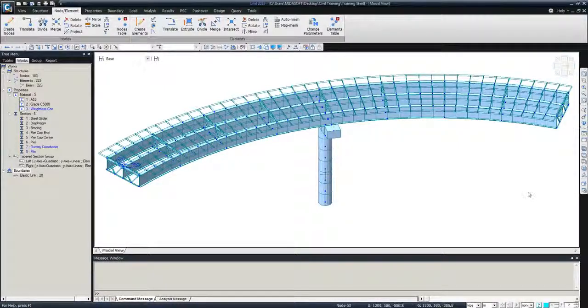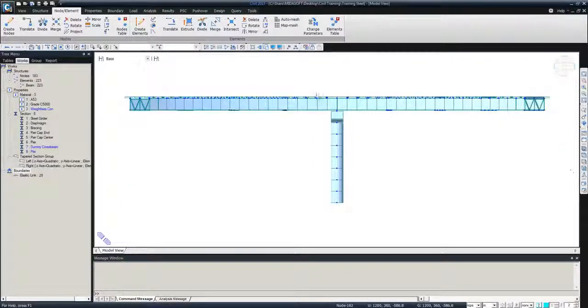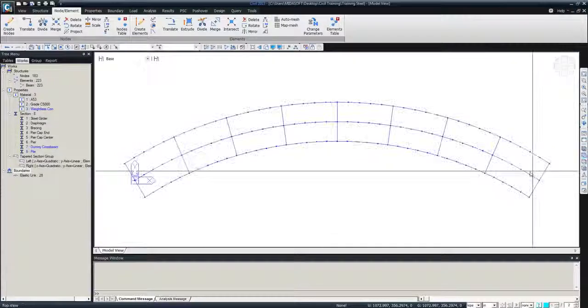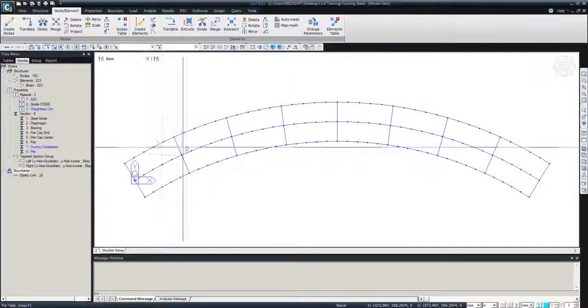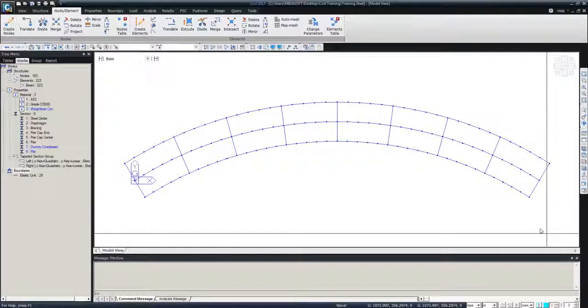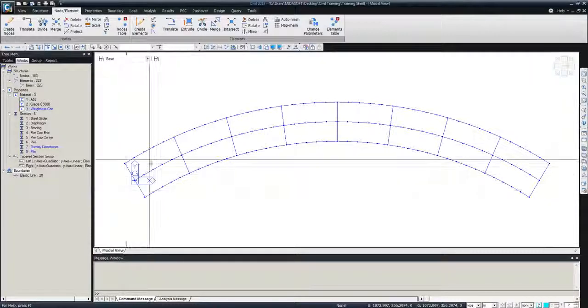See, here's the thing. If I turn this off and then just activate the top girder, what we see here is that most of the girders are left behind, and they are not connected to each other. So technically the girders are working separately. But when we have the concrete on top of the girder, one of the roles of the concrete is to keep them all together working as one system, not as individual elements. So we have to simulate that.